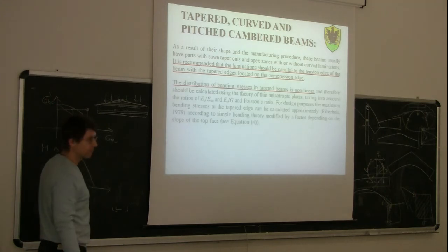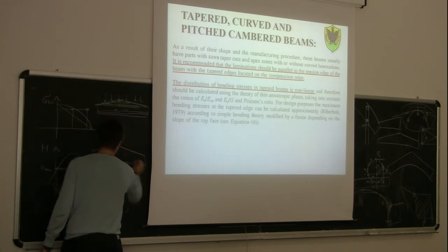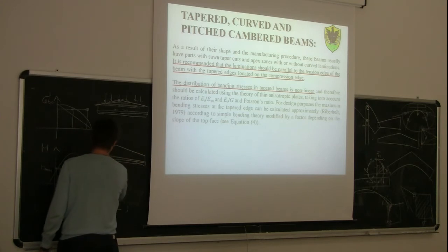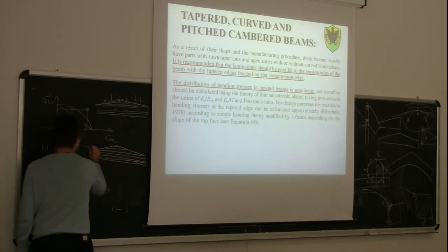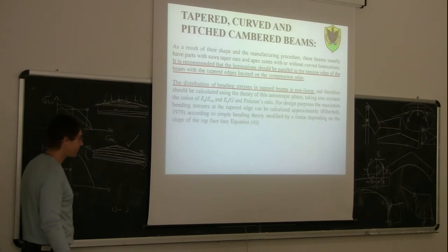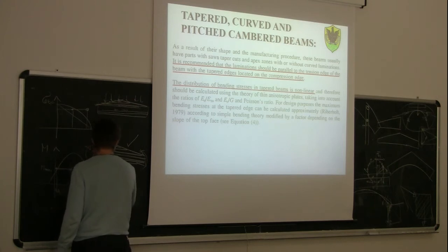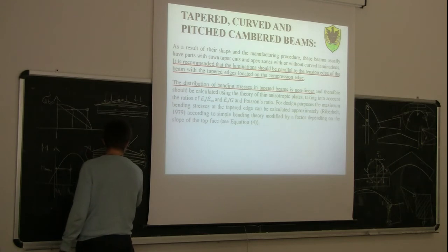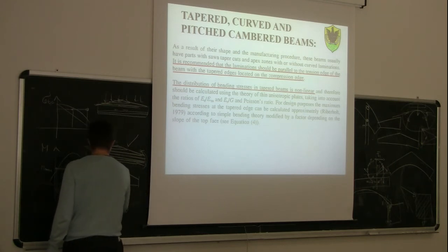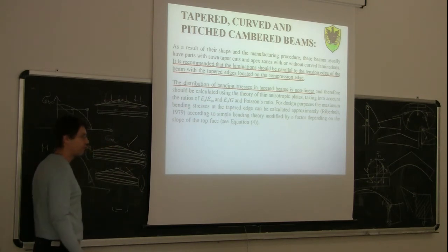So, again, for positive bending moment, this is okay. Instead, if we have a beam which we know is subjected mostly to negative bending moment, this solution is wrong, or should be avoided.